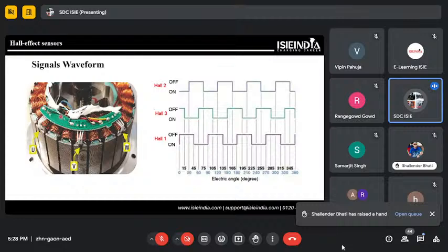Here in these three, we are giving a power supply source to each of the sensors, right? Positive and negative, and through each of the connections, you can find a blue wire, green wire, and yellow wire. It's getting the data of where the strong magnetic field was, where the north magnet was, where the south magnet was. As per the responses, it will create a waveform like this.